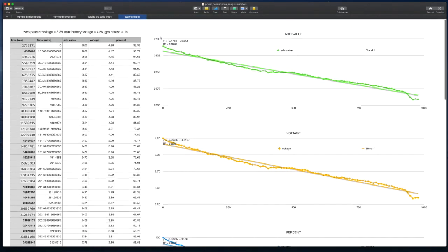And you can see the analog digital converter value. The left-hand side is when the battery's at 100% and we're functioning, and then we're sampling every 10 minutes, we get another point. Over on the right-hand side, we get the last point and then the board turned off. So it's no longer functioning. And so using the right-hand side, this is where you can find the 0-point voltage value. So what's the value of the voltage for 0%? This is the value of the voltage you can feed in the constructor for the battery class, and that's their 0% voltage over on this side.